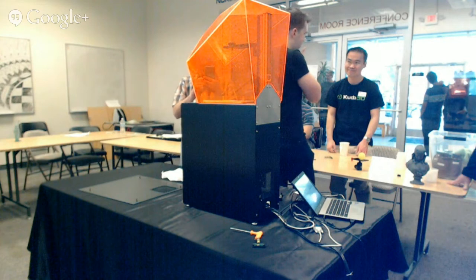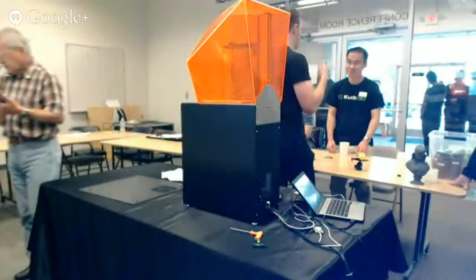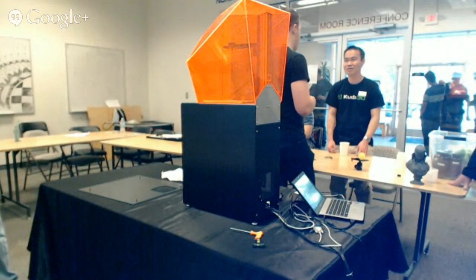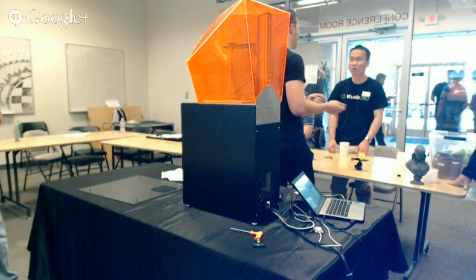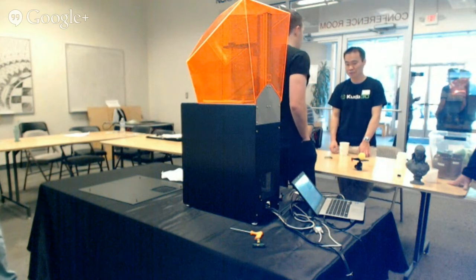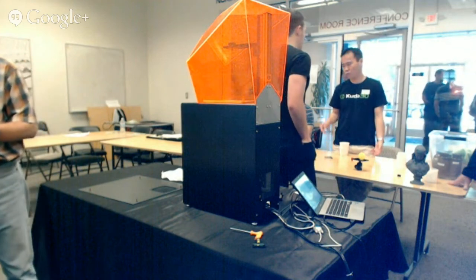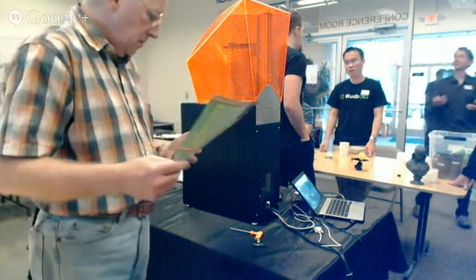More importantly, any resin is not a good fit for these rare parts. Even the strongest resin that you can buy today that I know of is brittle. 3D printing material is brittle. So when professionals use these prototypes and they have snap-fit parts, they print it so that the snap will work once or twice to determine that it's going to work, and we're good. And then we're going to go make it in ABS. They know that that's a property. You can never produce a production part.